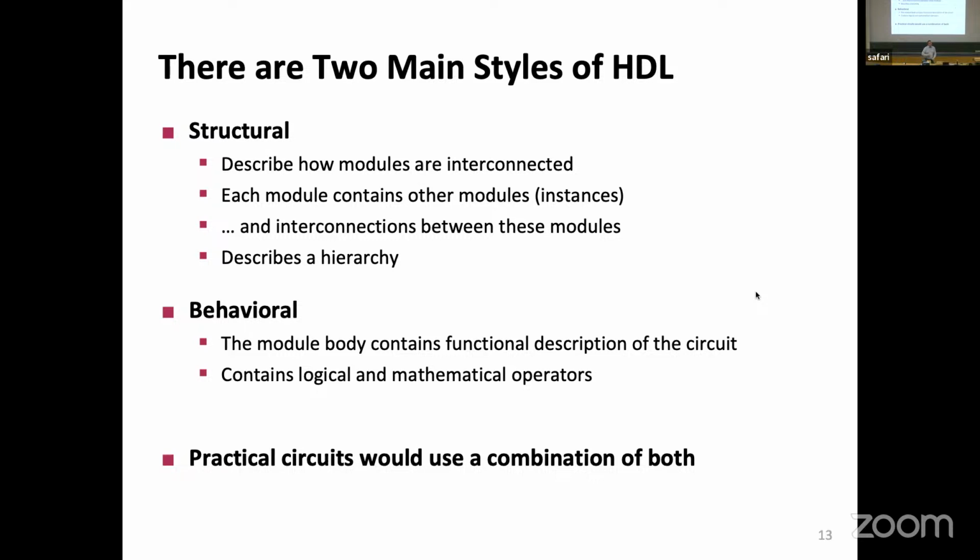So we will see that while we are writing our own code, practical circuits would use a combination of both. Sometimes you want to dictate a structure, and sometimes you want to infer a behavior. And you'll be going between them both. So it's not like everything you do will be either behavioral or structural. In most cases, you will use structural whenever it fits you, and whenever it is easier for you, you'll just say, here's a story, make something, I don't care. So we will start with structural, and we want to see how we are instantiating these modules.